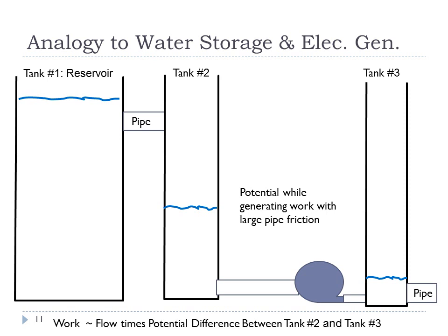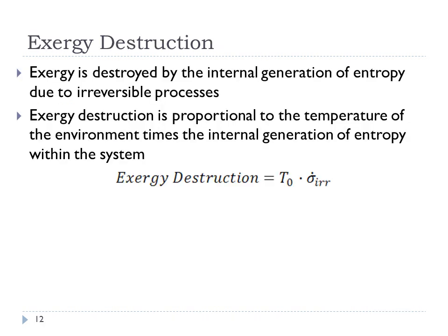There's going to be a maximum work that the turbine can actually output. That happens when, as you increase the flow rate, it is compensated by an equal amount of decrease in the height of the potential. Depending on what your system looks like, your work can look very parabolic, meaning there will be a maximum. And if you try to go even further, you'll find you get no actual work out of the turbine.